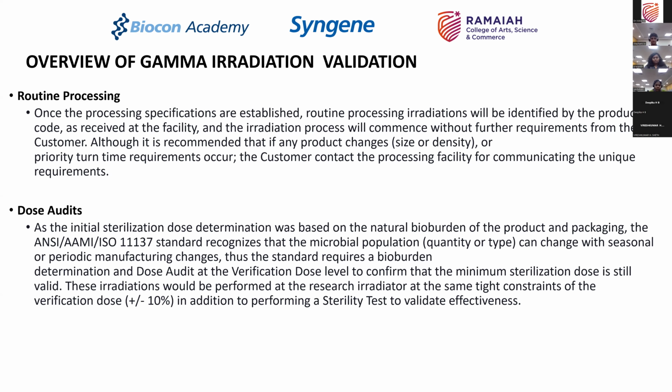Okay. Now, in such a routine processing, when he is doing 25 kilogray plus or minus 5 kilogray, he will take your load along with other loads which are in the similar range. They will be identified using a product code. So you will package it using a product code. He will put it inside the irradiator, which has got other products also, but they are all running on the same dosage rates, and he will subject it to gamma irradiation.